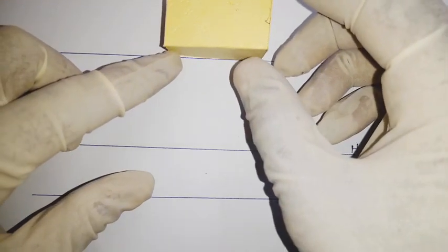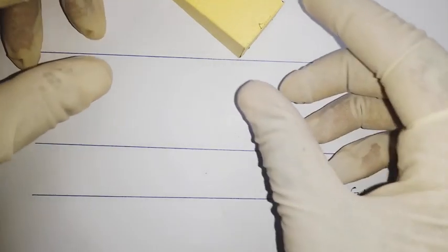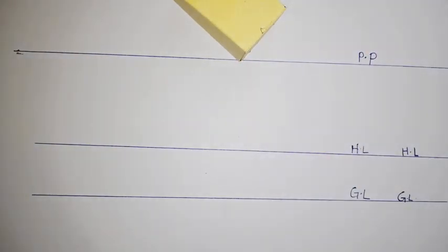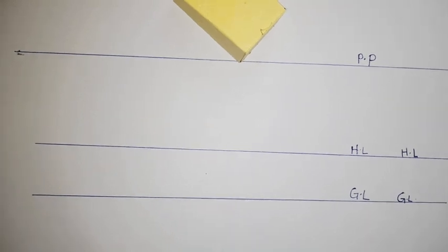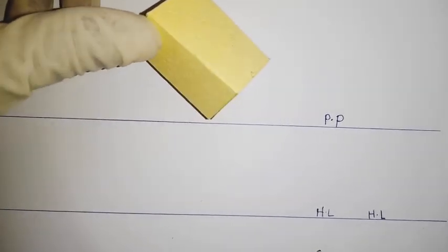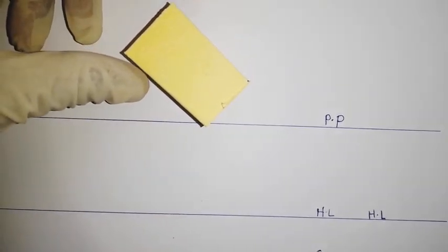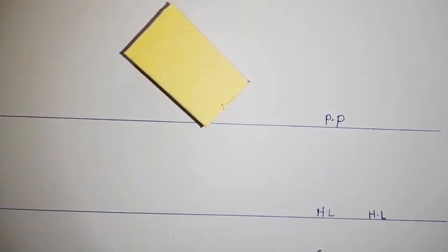it means we have to put it in such a way that one of the corners touches the plane. The reason why one of the corners must touch the plane is because we want to draw it in perspective, so that we see both sides, from the left hand side and also from the right hand side. So remember, this object here is a cuboid. It has a height, it has a base, and it has a what? Length. So we are going to draw such that we have 45 degrees on one side, and another 45 degrees on the other side.